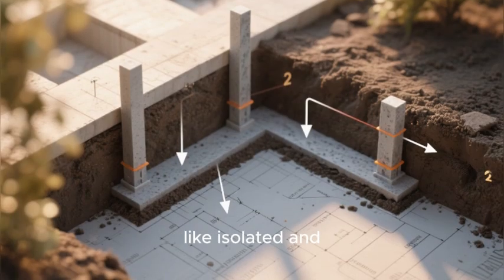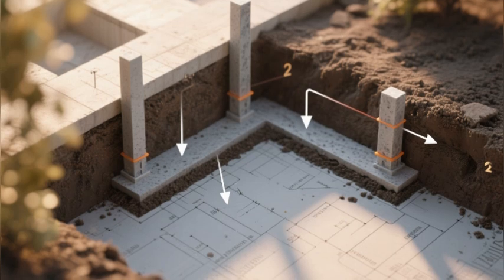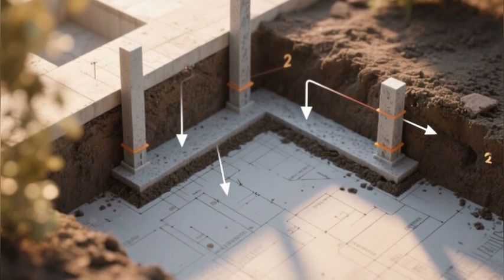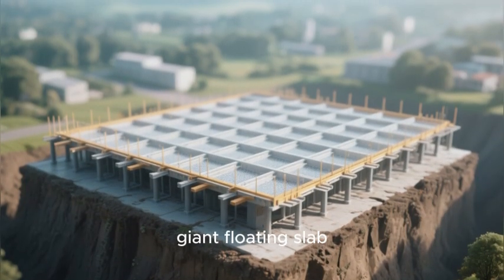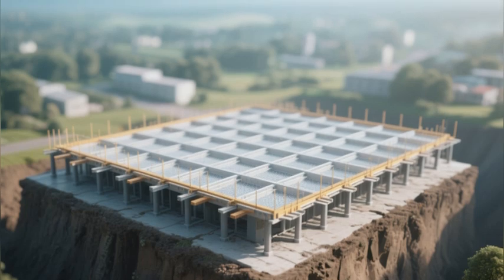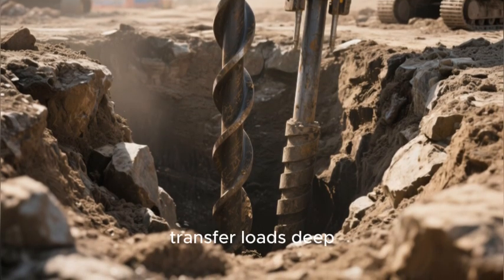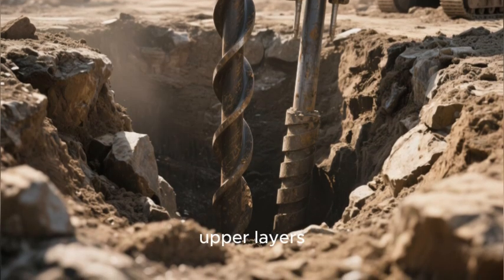To summarize the key takeaways: 1. Shallow foundations like isolated and strip footings spread loads laterally near the surface and are used in good soil conditions. 2. Mat foundations are used for heavy loads or poor soil, acting as a single, giant floating slab. 3. Deep foundations like driven piles and drilled shafts transfer loads deep underground to competent strata, bypassing weak upper layers.